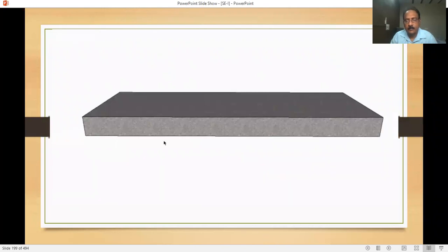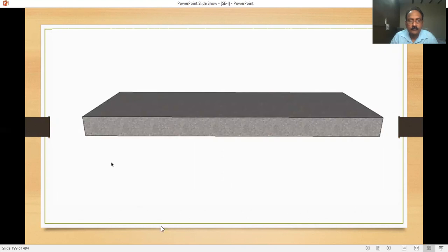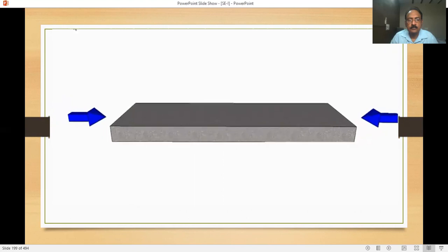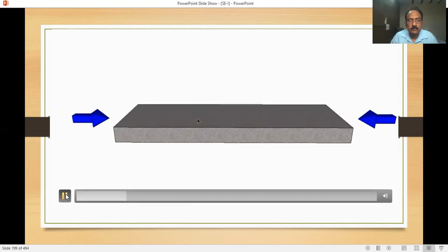What I want to show you today in this video is the strength and weakness of concrete and steel, and how we use them together as reinforced concrete to form a very strong structural member of our building. So essentially, this is our slab of concrete, and concrete is very strong when it's compressed or pushed together. Think about a force being pushed along the line of these arrows, pushing the concrete together. The concrete's going to stand up pretty well. It's not going to want to crack or anything.